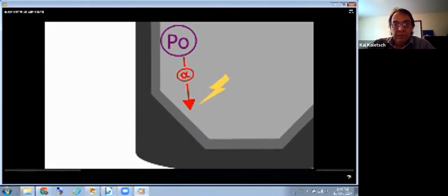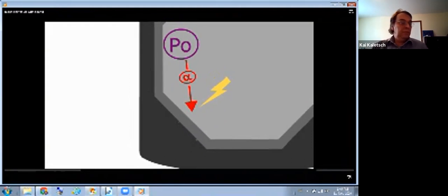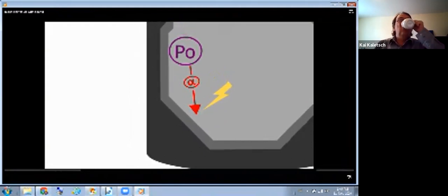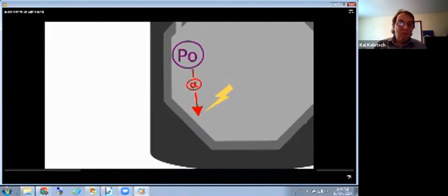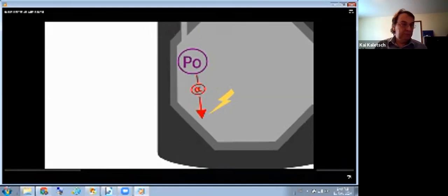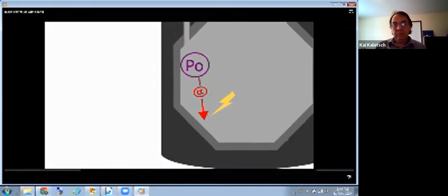The radon sniffer calculates how much radon progeny is stuck in the cell at any time, and can subtract that from the total number of counts. You then get a real-time measurement of the radon concentration in the air being sampled. However, there are some caveats to the previous statement.